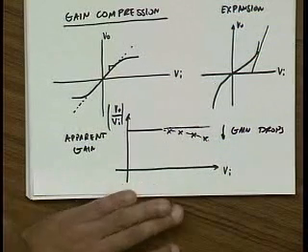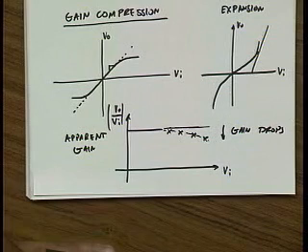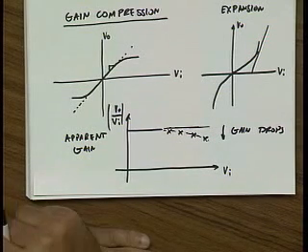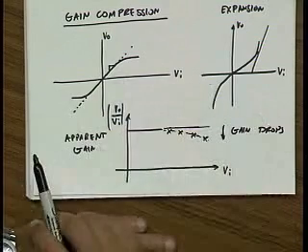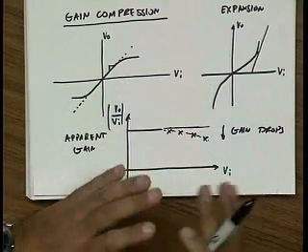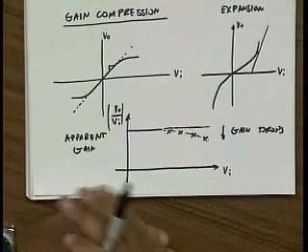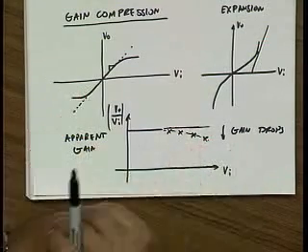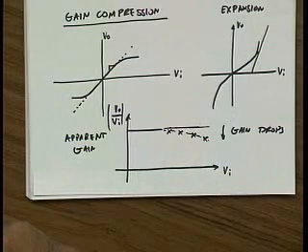Yes? You say high frequency, you mean high amplitude? Okay, thank you. High amplitude, yeah. Sorry about that. So here we're talking about essentially putting in signals which are in the passband of the amplifier. So effectively, they're either low frequency signals or they're signals within the passband, so there's no frequency effects going on. This is just due to the nonlinearity of the amplifier.